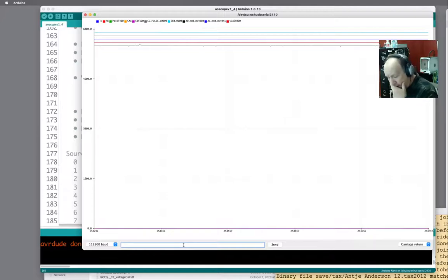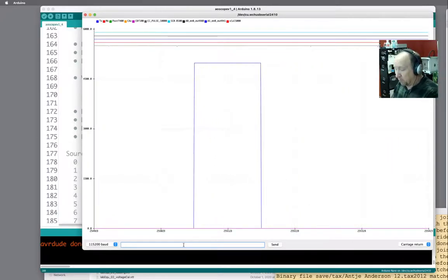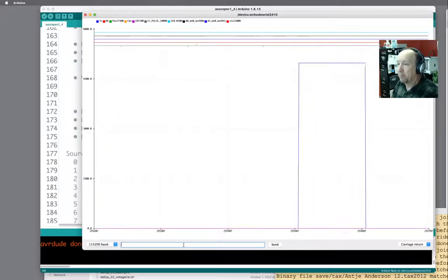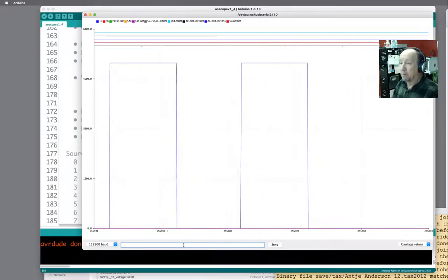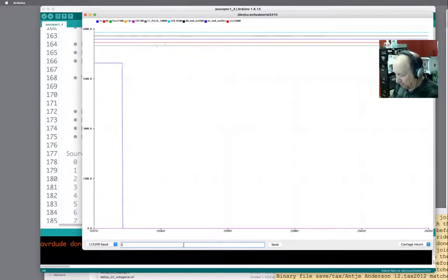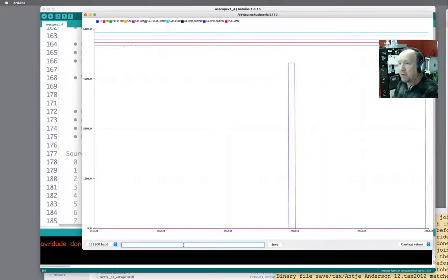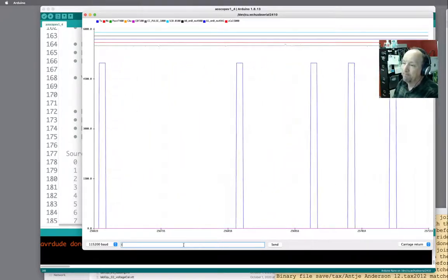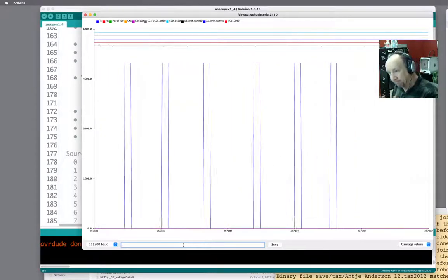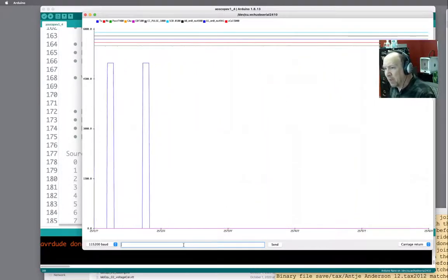Okay, so that's not so bad. Now I hate to keep typing these things in every time, because when you're working on electronics and you're feeding this into some other logic gate, you'll want to give it a pulse and look at something, give it a pulse. So if you ever just type an L and hit return, it'll give you that same pulse again. So it's really easy just to type an L and hit return, and it'll give you another pulse whenever you want one. So that's a full second. So let me go LP 1,000. That's the tenth of a second one. But again, I can just hit an L and return, so I can generate pulses slowly. So you've got some simple logic output levels.